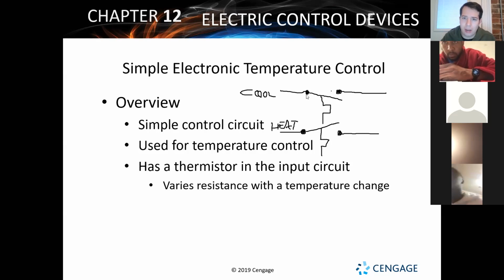Down here, the switch is down at 72, and as it gets closer and closer to 74, it's going to close and complete that path. Then 24 volts of electricity that's sitting on this side is going to be sent out to our different control components, whether that's our control circuit board, our thermistors, our contactors, or our relays, and that's what's going to turn on our different components.